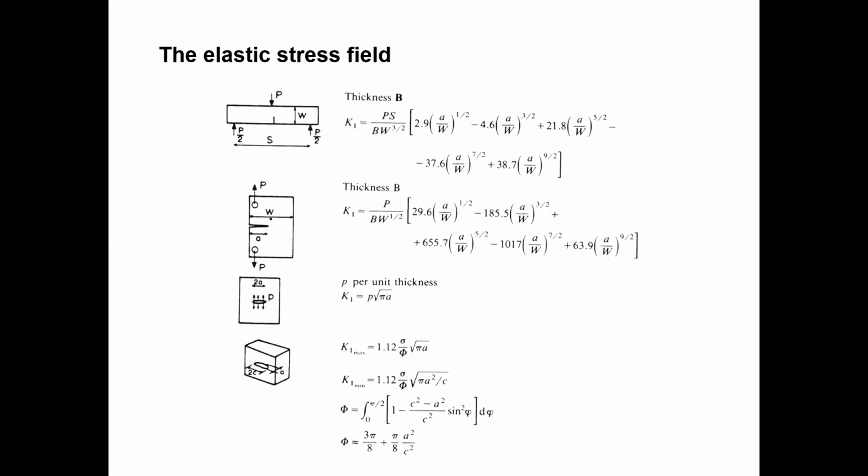If you remember, I told you about the crack growth rate. We will calculate it using this kind of specimen, and at that time they will use the K_I equation like this. If it is inside pressure, inside the crack you can see there is a pressure P, and outside there is nothing. Inside the crack there is a gas fill, so the pressure applies on the crack surface. This is the way you need to find out K_I.